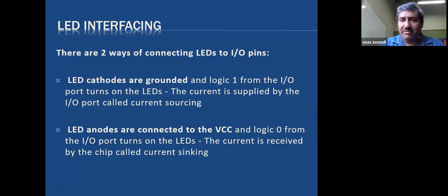All right. And someone may say, okay, I want to have one pin, say anode, connected to one IO pin, cathode connected to another IO pin. Okay. This is also a possible combination. You try this in the lab and see how you can turn on that LED. All right. But in that case, you utilize 2 pins of IO ports. Right? Sometimes the number of pins may matter, right, depending on the functions. So this is the widely used way.